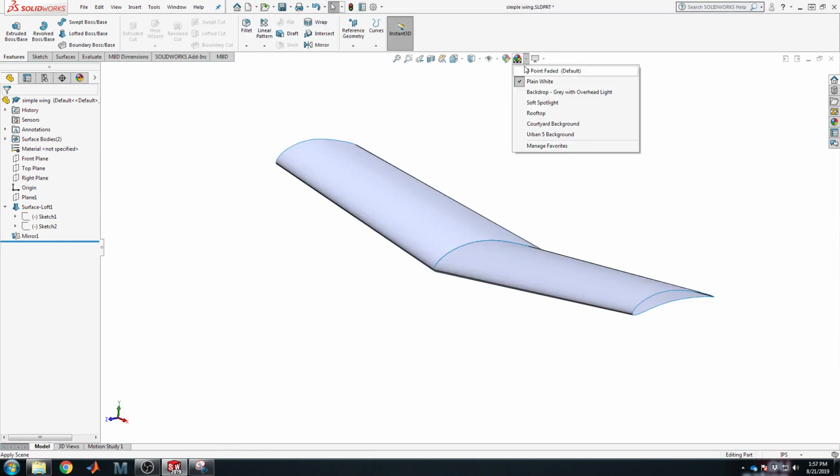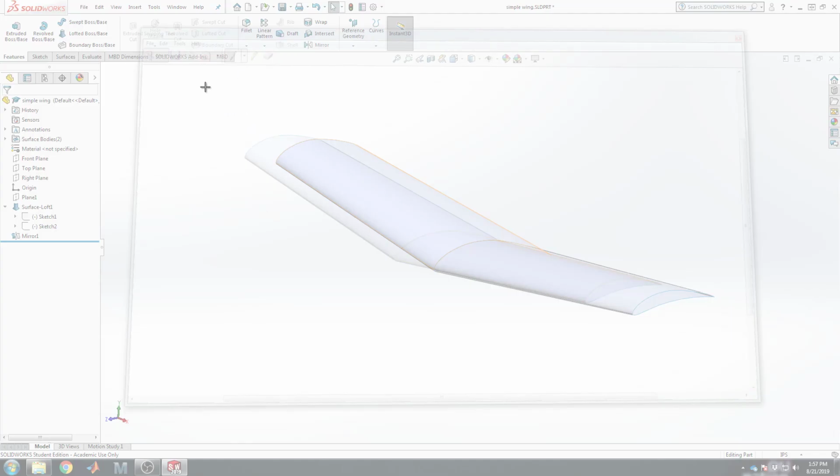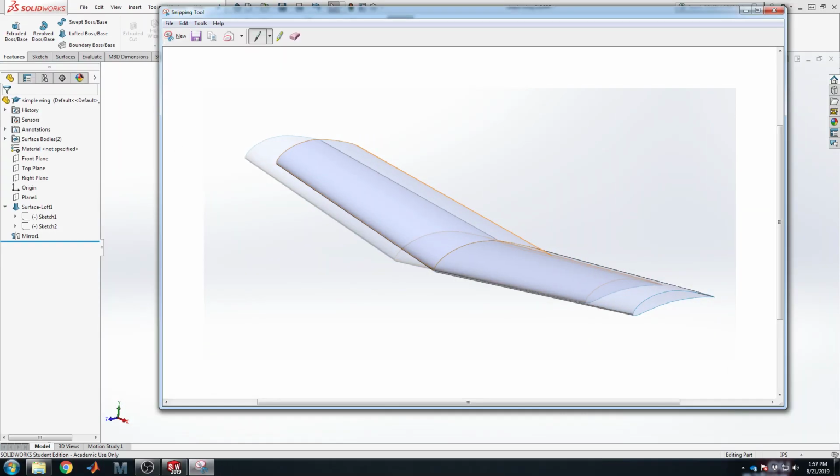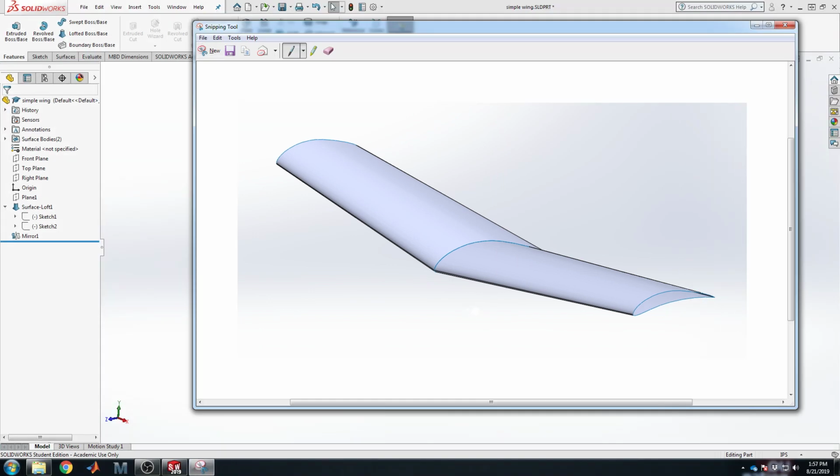Now let's turn back on the SolidWorks default and have a 3-point faded background, do the same thing again, retake the picture, and I want to grab the wing. That is what would be copied into your document. It's a bit worse than normal, so okay, let's let the computer have another chance. Still, we got rid of the ghosting, but now that's what goes into the document. See this gray background that's extremely obvious now if you're going to be going into a document.